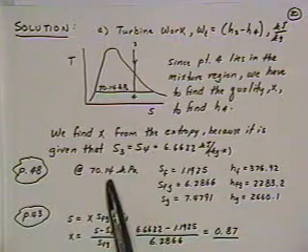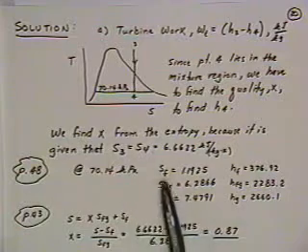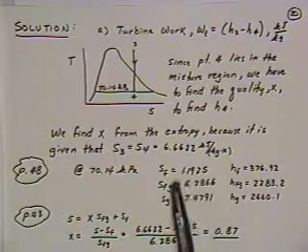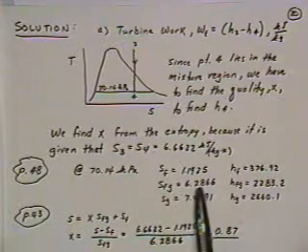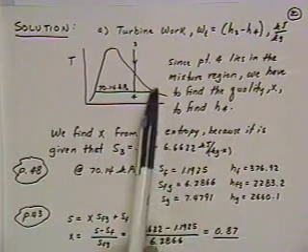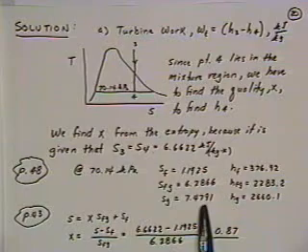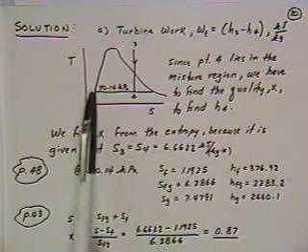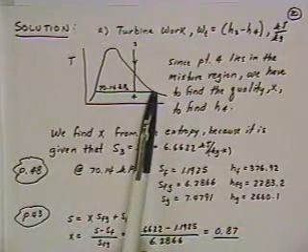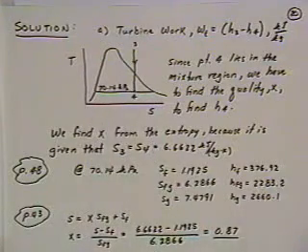So, page 48 on the tables, at the pressure value of 70.14 kilopascals, and we look up and find SF, which is the entropy at the saturated conditions, 1.1925, SFG 6.2866, SG, which is the entropy at this point here corresponding to the saturated vapor condition, is 7.4791. Similarly, HF is 376.92, HG is 2660.1, and so HFG, which is HG minus HF, is 2283.2.